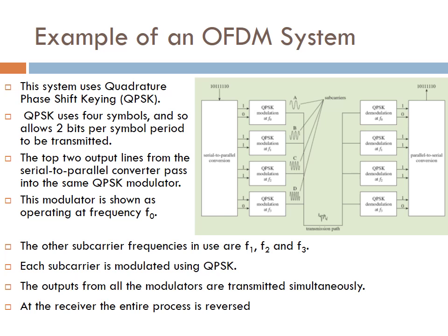In this example, there are four subcarriers, each of which takes one of four states. So the number of symbols available is 4 to the power 4, equal to 256 symbols. If there had been only two subcarriers, but each capable of taking one of four states, the number of symbols would have been 4 to the power 2, equal to 16.